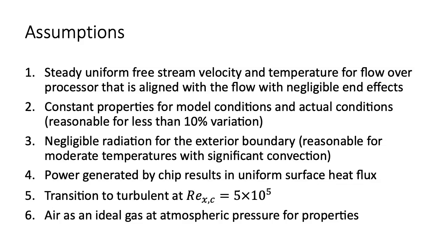Our fourth assumption is that all the power generated in the chip results in a uniform surface heat flux on the top of the chip. This is certainly not true, but it will give us a high estimate for the surface temperature. Thus, it will be a conservative estimate in terms of ensuring the chip does not exceed the maximum temperature.